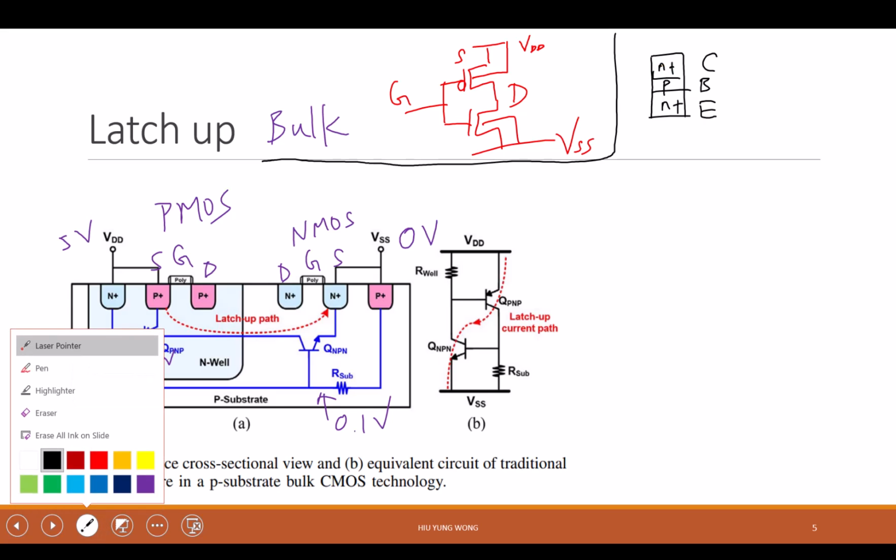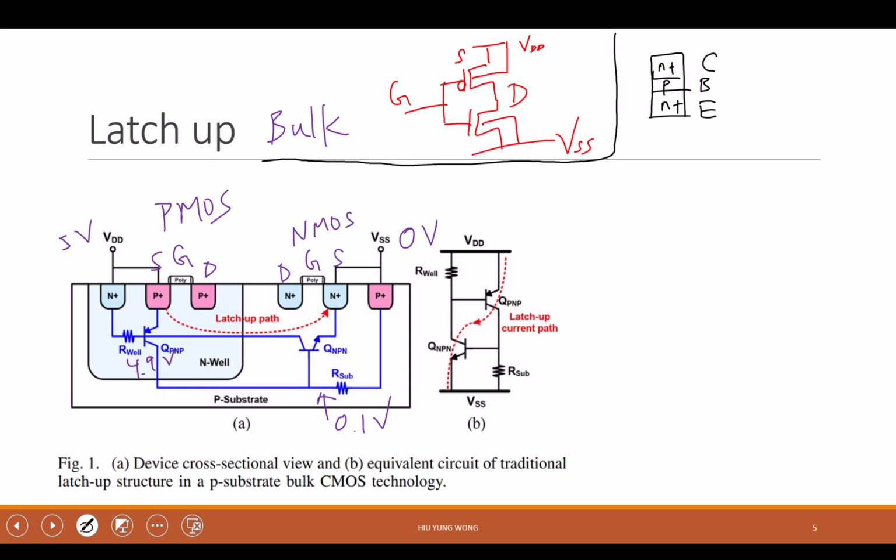The only thing I want to tell you is that this forms a transistor called PNP transistor, and its symbol is just like this. This is emitter, this is base, and this is the collector. And you have current called IC going in. This is very similar to the concept of an NMOS. You have the gate, you have the source, and you have the drain on top.